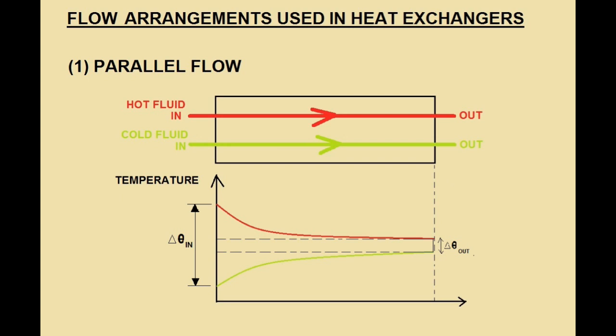One is the large temperature difference at the end causes large thermal stresses. Second is the temperature of the cold fluid exiting the heat exchanger never exceeds the lowest temperature of the hot liquid. This design is used when two liquids are required to be brought to nearly the same temperature.